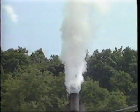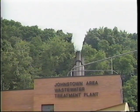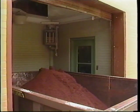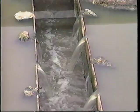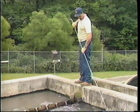The microorganisms contained in the digester prefer to eat most other organic matter before grease. If scum in the anaerobic digester becomes a real problem, it may be more effective to dispose of it by means of incineration or have it directed to a permitted landfill. The effluent weirs should be level and clean, allowing an even flow of wastewater to discharge over the entire course of the weirs. Measures should be taken immediately if weirs are uneven, clogged with solids, or become leaky.